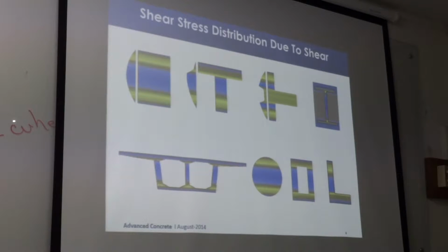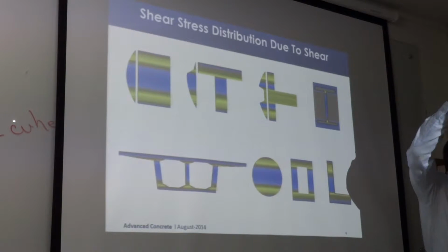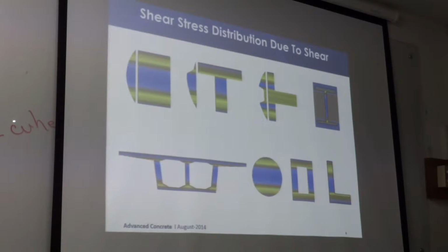Right? And this is exactly what we do in flat slabs or slabs where the punching shear is very high. We put steel sections crossing, like a grillage in the plan, and all of the shear problem goes away because steel takes all the shear, and steel is very good in shear, especially the web. Flanges take nothing because flanges are far, that is zero rotation. So in a steel beam, all of the bending is taken by flanges, all of the shear is taken by web.